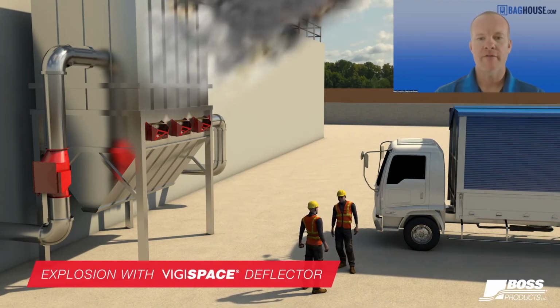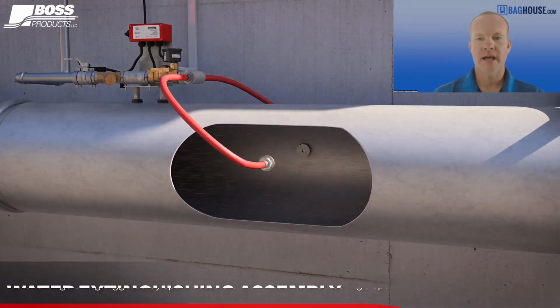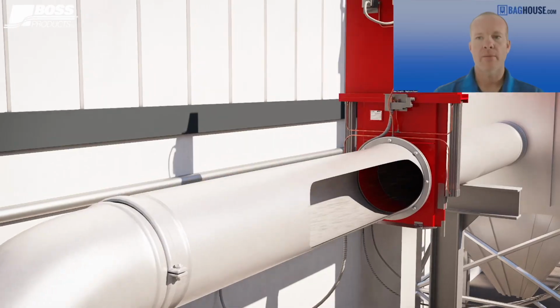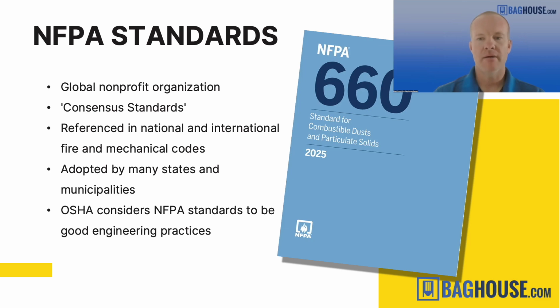And then finally, you have fire prevention requirements. Usually that comes in the form of a spark detection and water extinguishing system, or a mechanical fire break shutter, or some kind of a chemical suppression system. So those are the three big elements that are required in any dust collection system doing combustible dust. So if you have a wood shop, you're most likely required to comply with these.